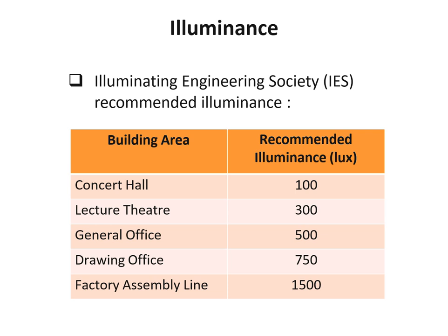Similarly, maybe a restaurant. Some of them might go 100, 150, and so on, because it's more about creating the ambience. And for a concert hall, you want the majority of the attention to be on the stage, right? So the stage itself will have a different lux requirement compared to the seating area, and it's dimmable. Okay, so general office areas will be 500 generally.